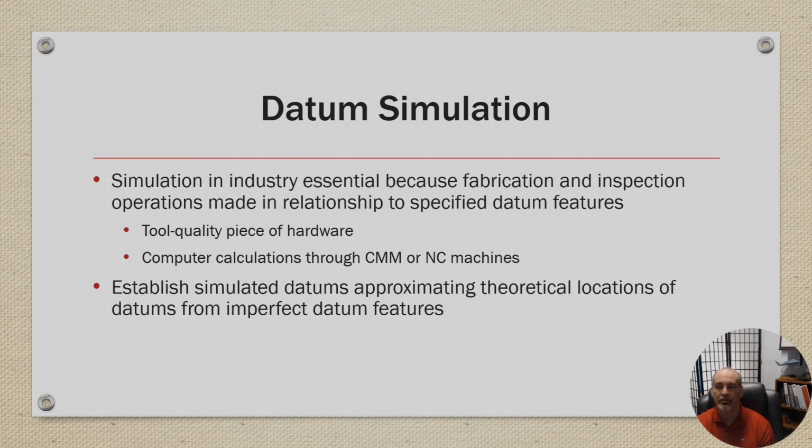Okay, so say you had a cast bowl and it has 3 feet on it, and you can reliably say, okay, well, these 3 feet are cast, so they're irregular, but I want those to be my datum features, and I clamp it to a table. The table becomes our simulator of tooling to make that flat so that I can machine the top of the cast iron bowl parallel to where the feet contact our simulated datum, being the table of the machine.